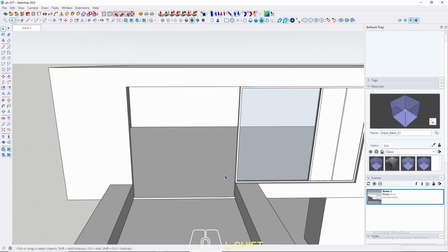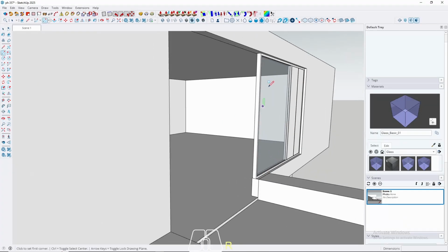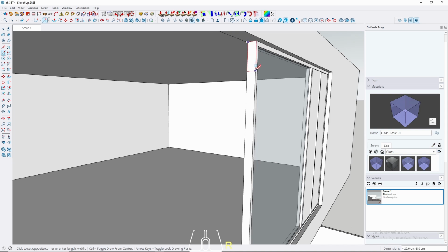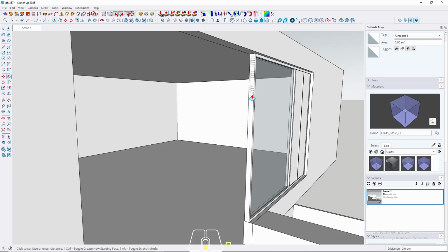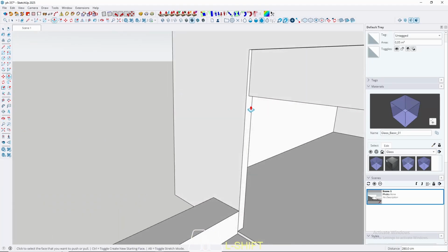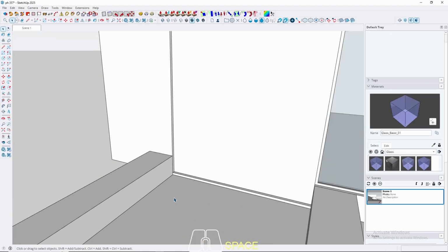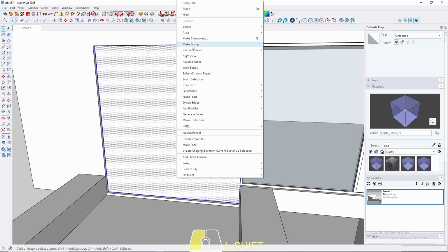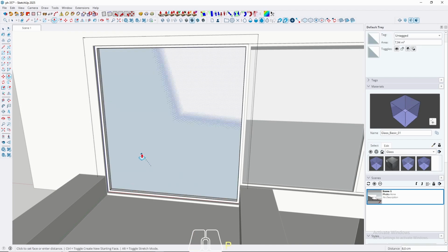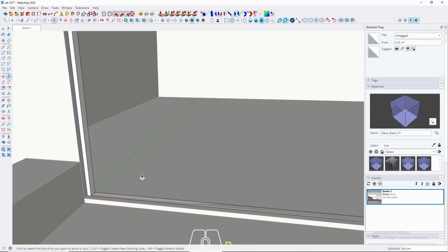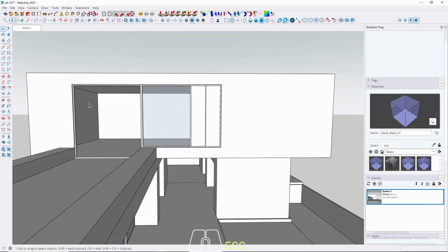And then this for window frame, door frame, sorry. Let's make the frame. Let's take the reference from this existing frame, push it to the left side, and then pull it to the ground or to the floor. Sorry. Make it group and offset 4 centimeter. Push it to the floor, and then that's it. We have a door frame.